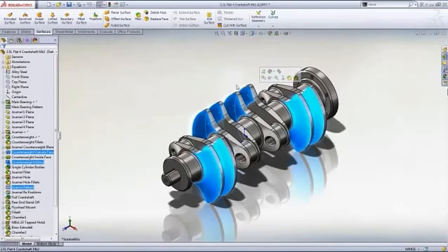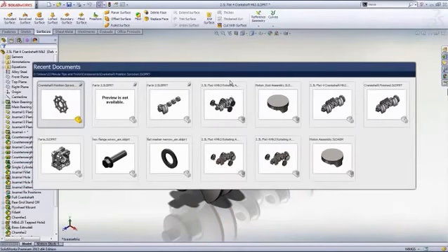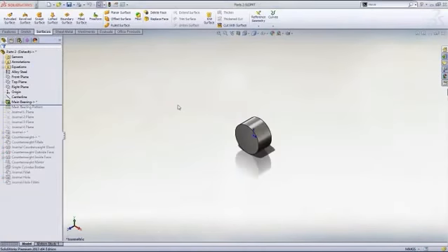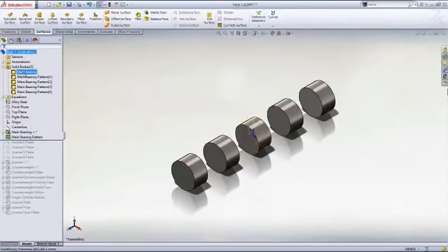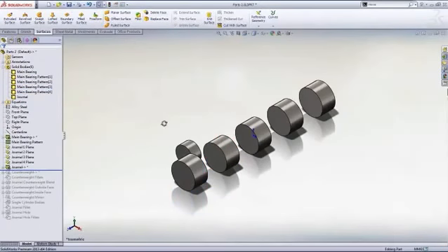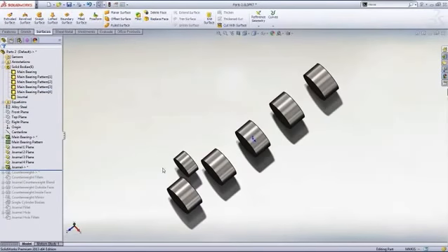I'm going to open this design in an earlier state to explore this concept. In this design, I've started with a simple cylinder for the bearing surface. Then I've patterned that, and you'll notice in doing so, I've created a part with multiple bodies. In fact, when I did this, SOLIDWORKS revealed a folder containing all the individual solids. Next, I created the journal where the connecting rod attaches out in space, also as a separate body.